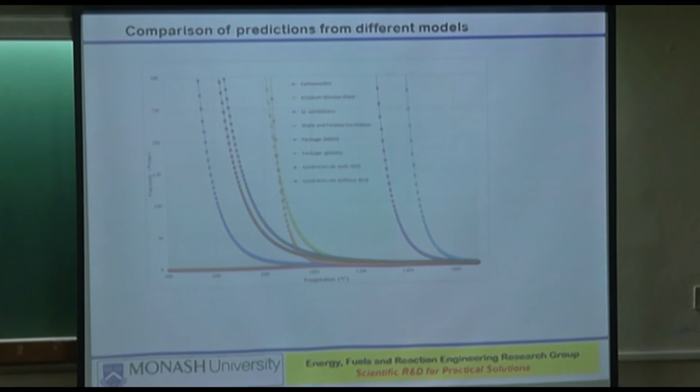We have to change the electricity cables, because you are now looking at large cables, because the current carrying capacity has to be reflected in that. So, a bit of interaction with the electrical engineering people. And then the biggest challenge is how to scavenge all the oxygen, otherwise oxygen will eat out the molybdenum.